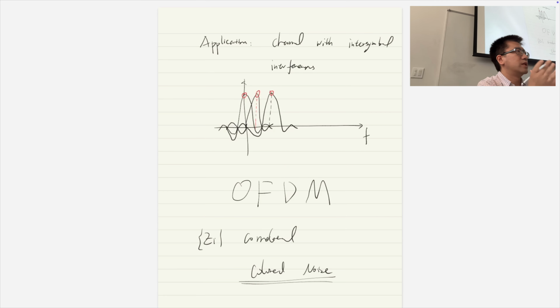Oh, by the way, everything we talked about here we can do using the capacity formula, half times log of 1 plus SNR. But in practice for communication, for those of you who have learned communication before, we know that we do not use Gaussian codewords. Therefore, it may not be possible to directly use the capacity formula. Although we can approximately use it, and that is okay, accurately we cannot say that we use the capacity formula.